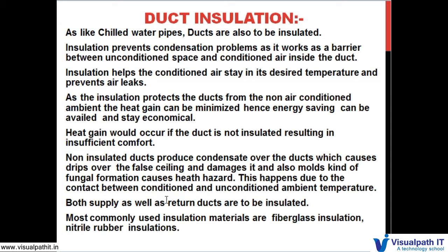Both supply as well as return ducts are to be insulated. Most commonly used insulation materials are fiberglass insulation and nitrile rubber insulation. Let us look into some pictures of duct sweating.